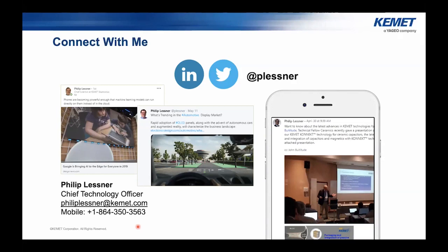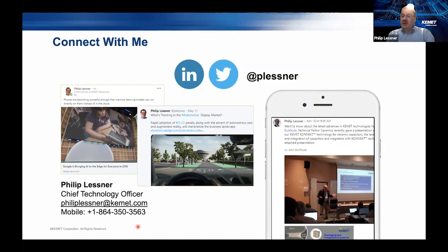All right. So one of our favorite topics, hermetically sealed capacitors. Are the new through-hole hybrid polymers hermetically sealed? Or can you comment a little bit, Phil, about some of our hermetically sealed options, leaded and surface mount? Right. So the only true hermetic seal capacitors we have are the tantalum hermetic seal capacitors, the T550 and 551 series. Those are truly hermetically sealed with a glass to metal seal.